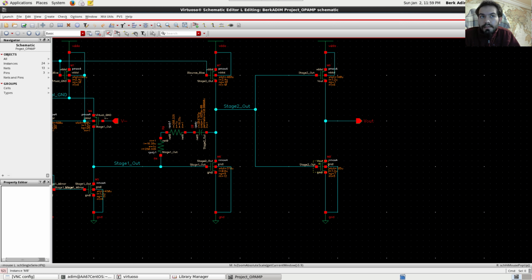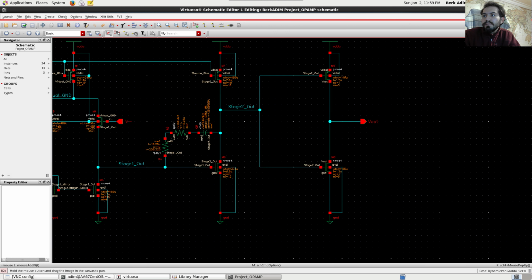And actually, the effective gain at the third stage will decrease considerably. So actually, connecting the Miller capacitance to the third stage can hinder our stability at common mode input corners of 0 volts and 4 volts. So we didn't do that.